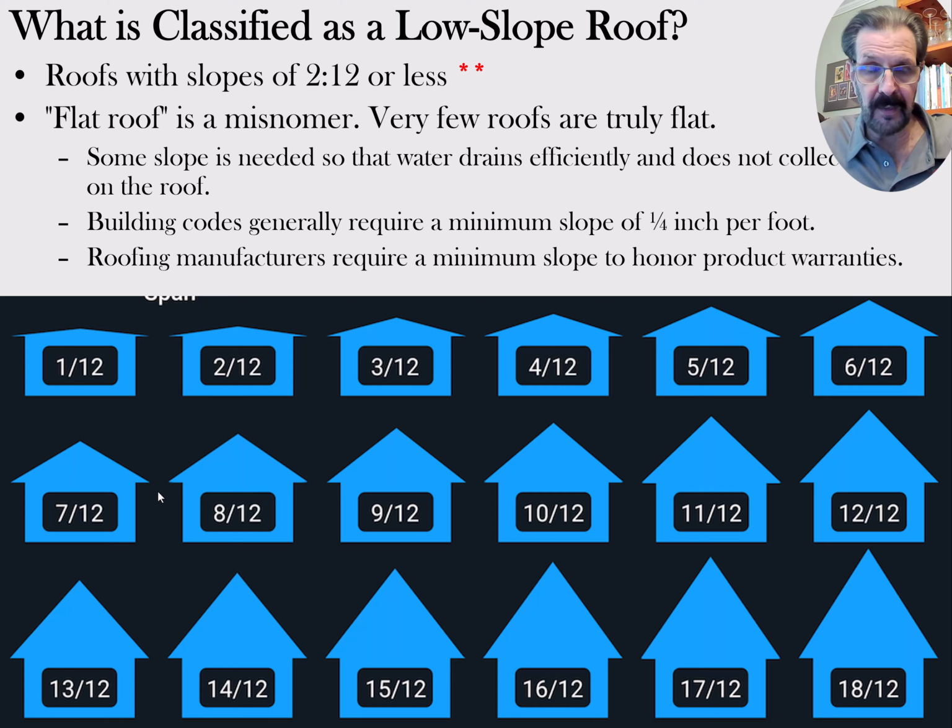But in a heavy rain zone like Louisiana, where we can get very heavy rain all at once, a steep roof can be a good thing. The water's not hanging around long enough to leak. I've seen steep roofs with a bullet hole in them that aren't leaking because the water's running down the roof so fast. So there are pros and cons. If you have high, straight line winds, the steep roof takes a beating, whereas on a low slope roof, the high winds flowing across the top can literally suck the roofing materials off the roof. So there are different issues to worry about with high wind for steep roofs compared to low slope roofs.